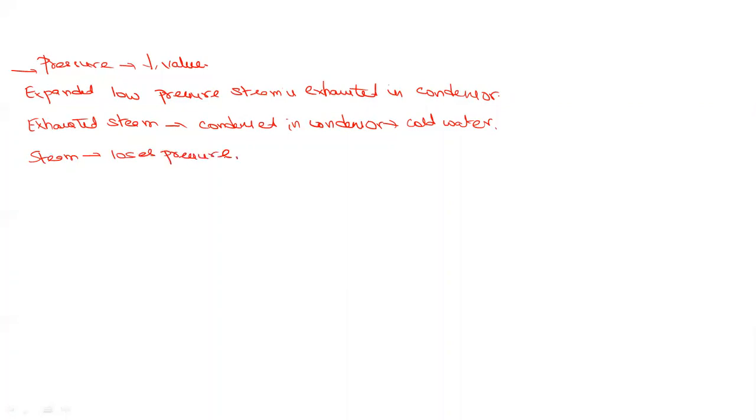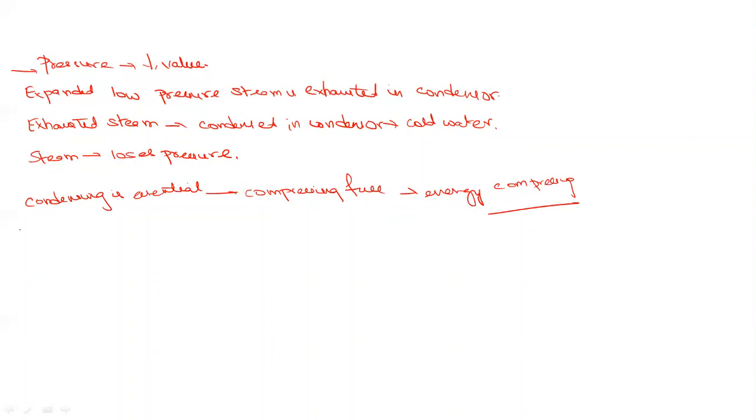Condensing is essential because compressing a fluid in the gaseous state requires a huge amount of energy with respect to the energy required for compressing a liquid. Thus, condensing increases the efficiency of the cycle.